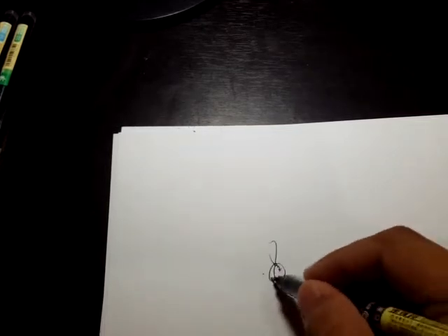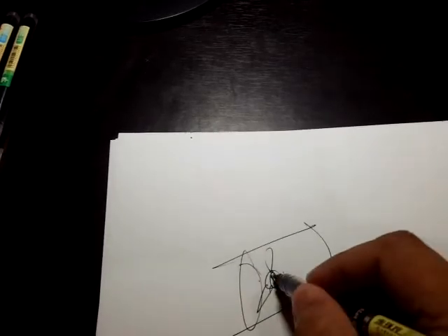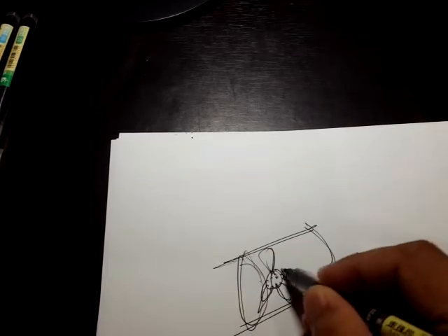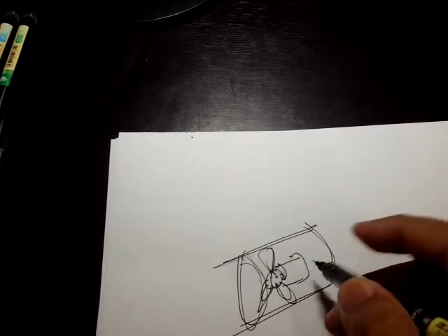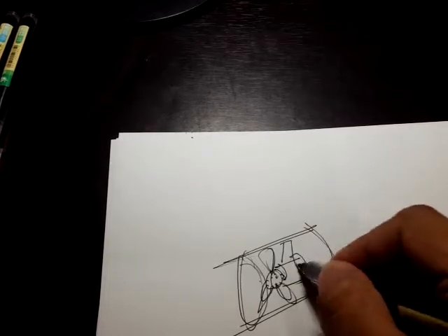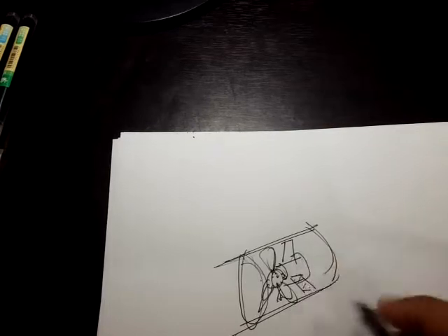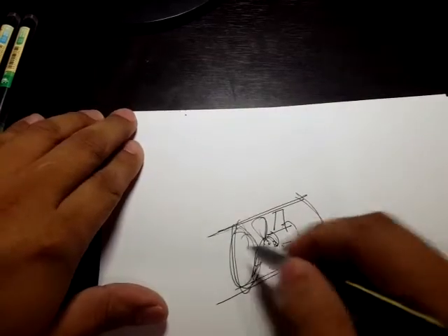So that vane guides the airflow and somehow improves the properties, or the performance rather. Right. So here's our propeller fan, and if we have this cylindrical housing, that's going to be a tube axial fan, and if we have these guide vanes, that's what we call a vane axial fan.